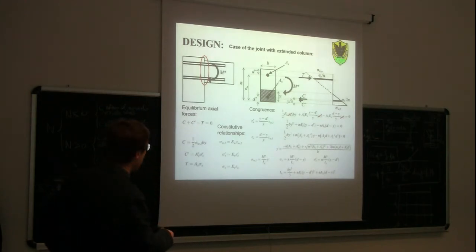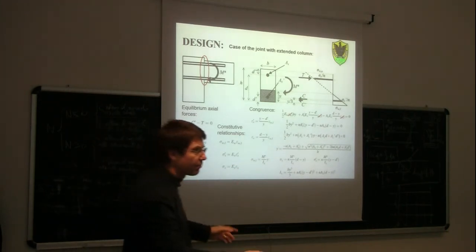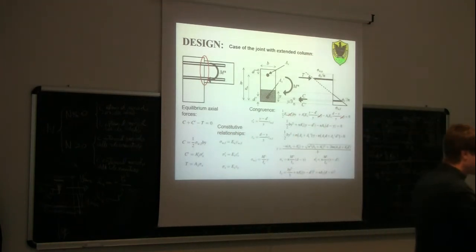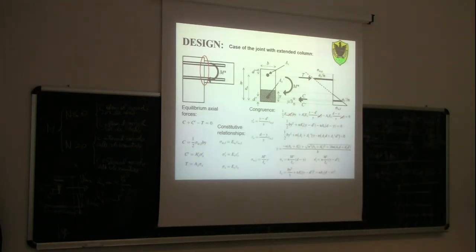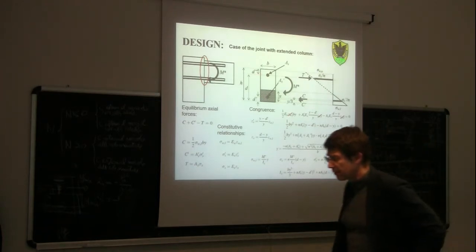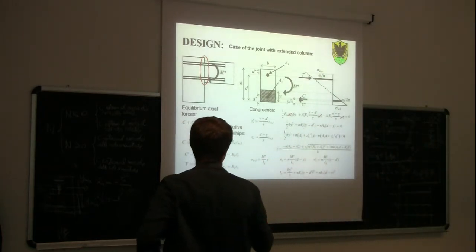So you have your portal frame, for example. You will start your design, so you have a portal frame. You analyze the portal frame with software or by hand, whatever you want. Then you will find the bending moment in the connection there. And from the bending moment, you will use this formula here to calculate the stress distribution in the wood and the actual tensile and compression force in the epoxy bars. Then you will have to design the epoxy bars for this tensile force obtained from this formula here.